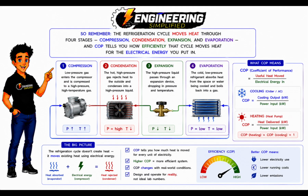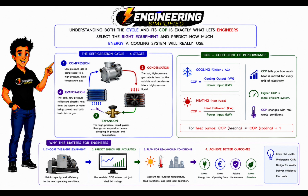So remember, the refrigeration cycle moves heat through 4 stages: compression, condensation, expansion, and evaporation. And COP tells you how efficiently that cycle moves heat for the electrical energy you put in. Understanding both the cycle and its COP is exactly what lets engineers select the right equipment and predict how much energy a cooling system will really use.